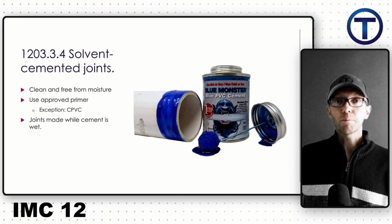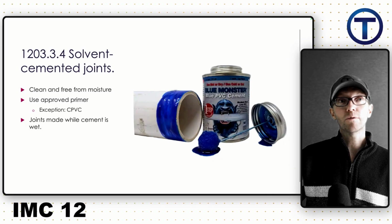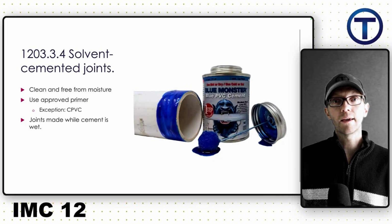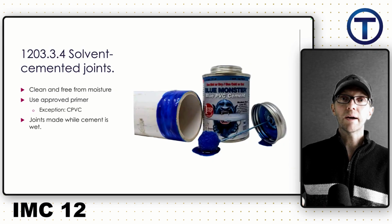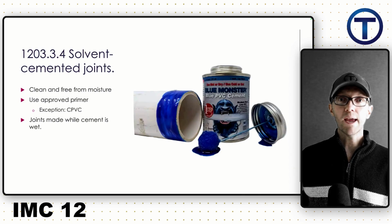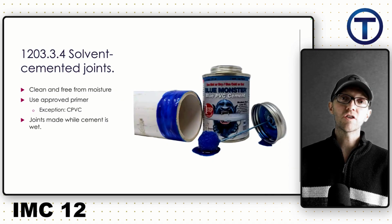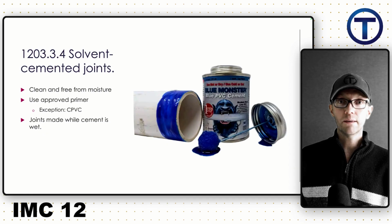Drainage pipe is not for pressure. It says it right on the pipe. And while we do pressurize it for a test, we only go to 5 or 6 psi. Here, we're talking about a pressurized system. And so, primer that baby. Lots of primer on that. Lots of glue. Make sure you get a good, solid joint because this is going to be under pressure.